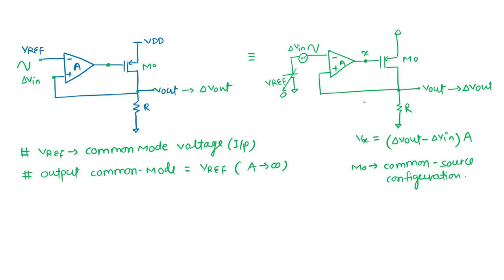For the common source, there is no loading because current is zero. Even if there is loading, we will see this side impedance, but as this side impedance is infinite, we are not worried about that. So directly we can say the gain from X to out.